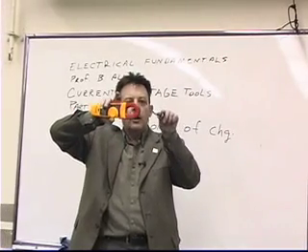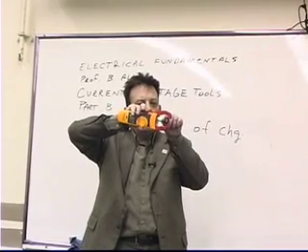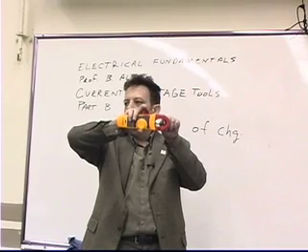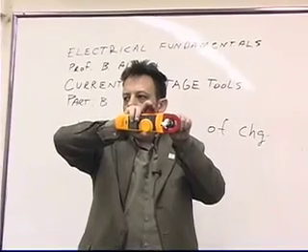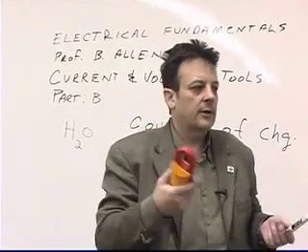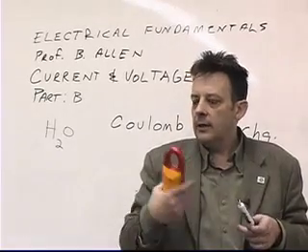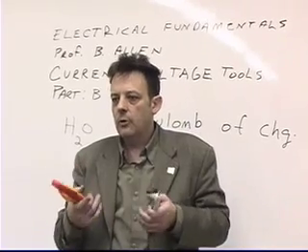You're opening up this meter, putting it over this wire, and closing it, but the wire isn't even touching the meter. So how's it measuring anything? Well, the way it's measuring something is because there's a magnetic field around the wire. And it uses a phenomenon called the Hall effect to measure the current.